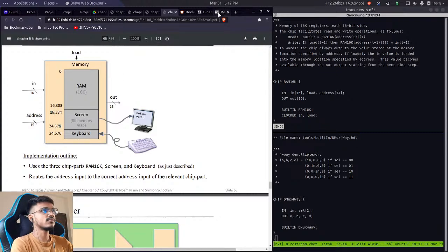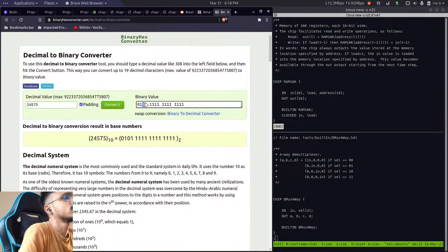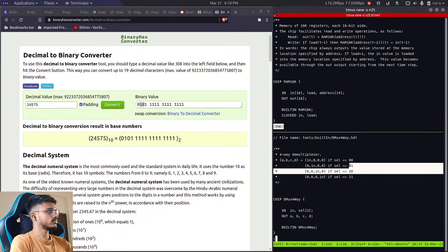And if both of these bits are 1, that means the number is either this one or greater than 24576. So in this case, we are assuming that we are providing the correct address each time to this memory. It won't be outside of this range, 0 to 24576. So in that case, we can just use these 2 bits for our logic.